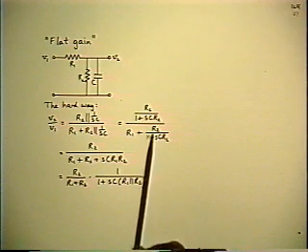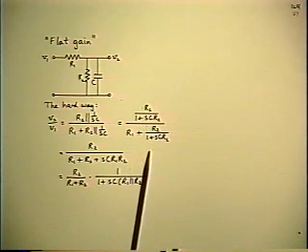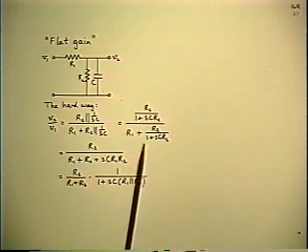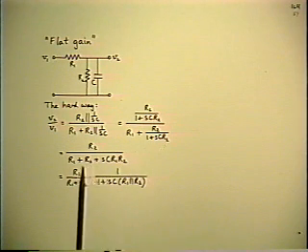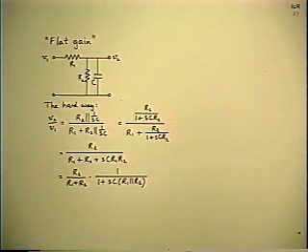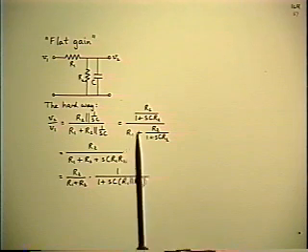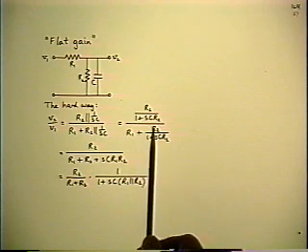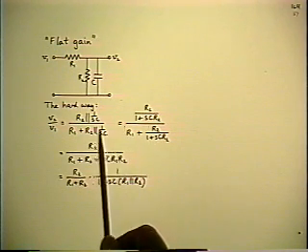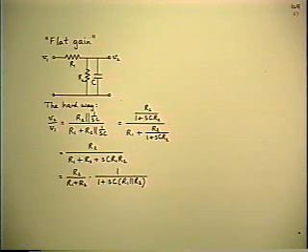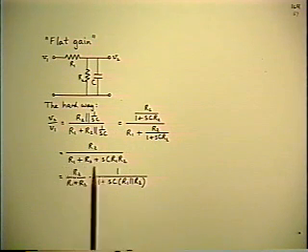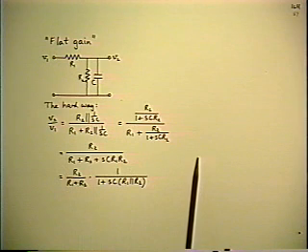The next line of algebra means you get rid of the internal fractions, because the objective is to write the answer as a ratio of polynomials in complex frequency. That is, you want the numerator to be in the form of 1 plus s squared plus s cubed, etc. You want the denominator to be in the same polynomial form.